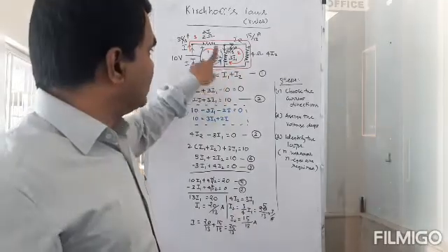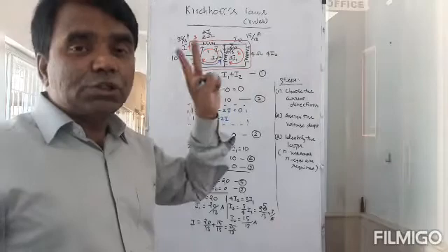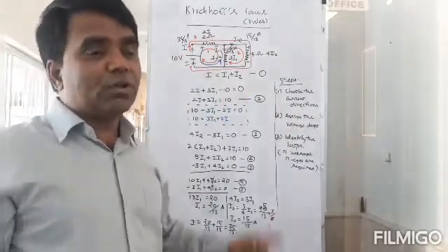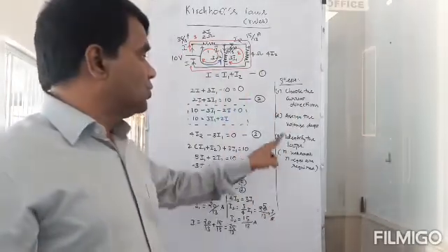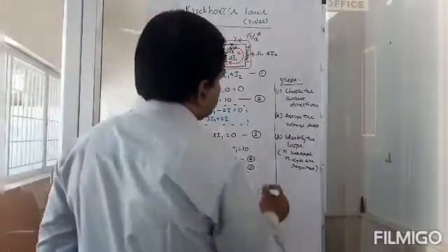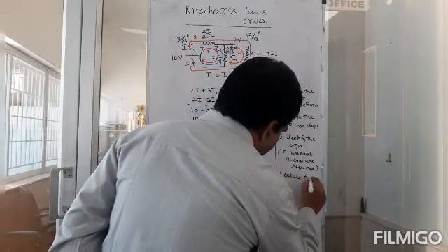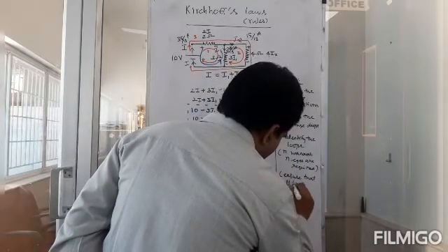But in here I got only one current equation. I have 3 unknowns, so I require 2 more equations. So I need to identify 2 loops. So identify the loops. Okay. What is the condition to identify the loops? Ensure that all the branches are covered.